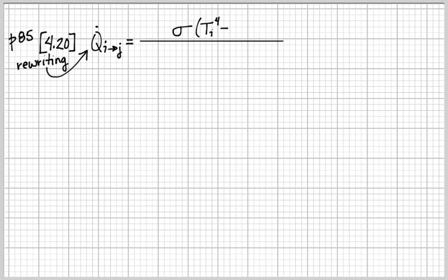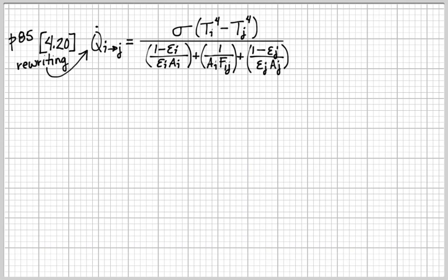Okay, so on page 85, we are going to rewrite the radiant transfer Qij. And it's going to get pretty dense, right? So you're seeing up on the top, in the numerator, something very close to the Stefan-Boltzmann representation for all the energy under the curve. But we're using two different surfaces at this point. We're using the surface temperature of i minus the surface temperature of j, times the Stefan-Boltzmann constant.